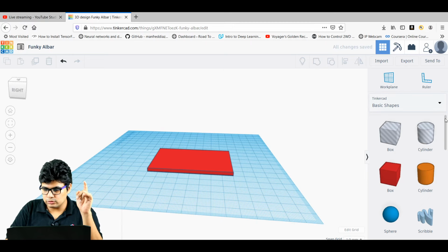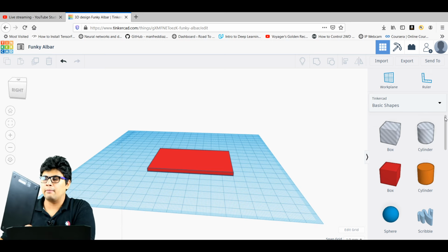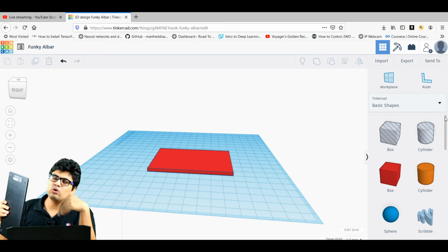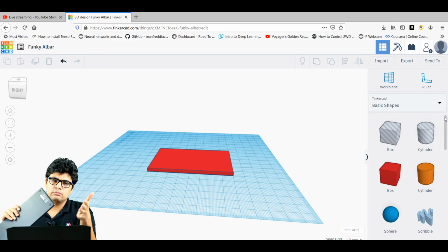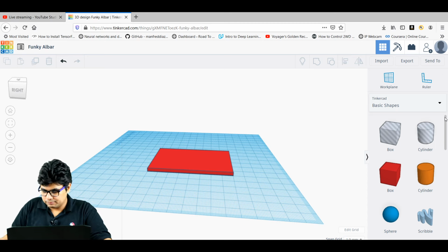We will use something called a fillet here. If you see here, this is my drawing tab, and you can see the edge is rounded from here. If it were sharper, it would look ugly and it can also damage. You may see that on the edges of tables also. These are all rounded, and these are called fillets. We will do the fillet for the edges of this base block.